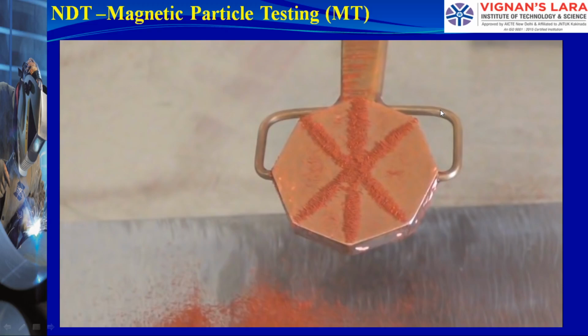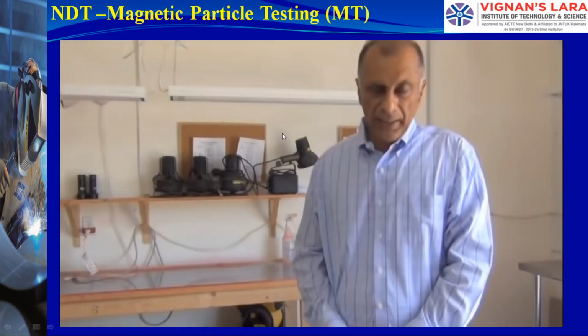The dry powder inspection is very simple, easy to use. One of the main advantages of the dry powder is that it can be used at high temperatures up to 600 degrees. And again, the most important things in this inspection are to make sure the yoke is good and there is enough light on the part being inspected. Now we will go to the next two videos, which will be on the wet MT. The first one will be on wet visible MT, and the second one will be on wet fluorescent MT. Thank you.